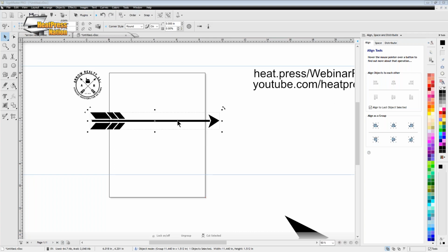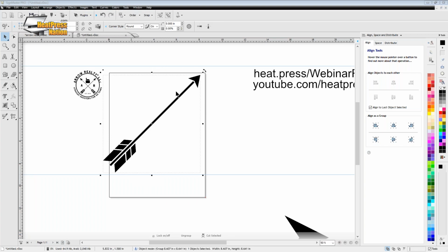I'm going to rotate this about 45 degrees. Now it is going to lock. And I don't know if you see on the screen in very tiny letters, it'll lock in at 22.5 degrees, it'll lock again or snap at 45, it'll snap at 67.5 and it'll snap at 90. So using that, I'm just going to snap it at 45.